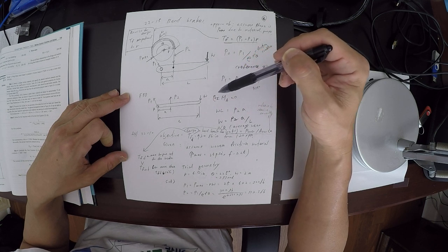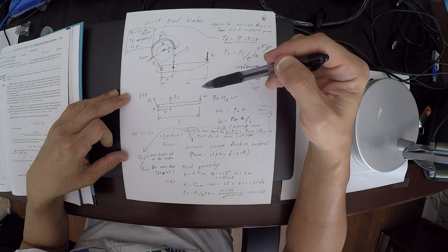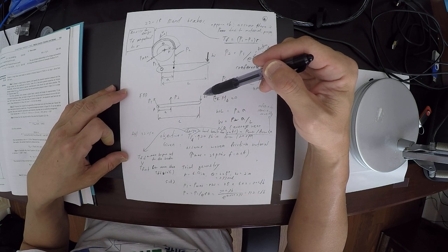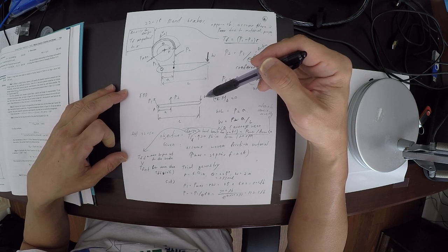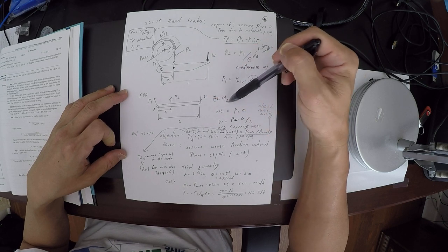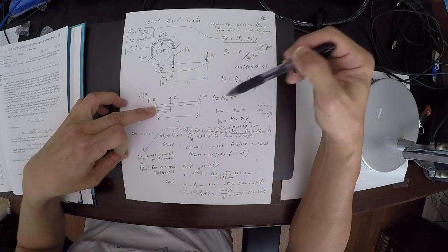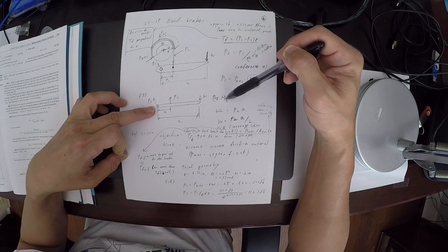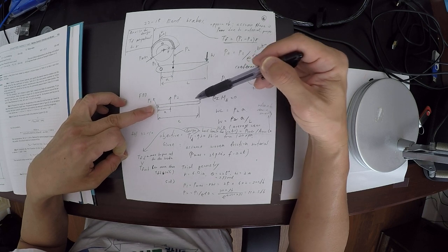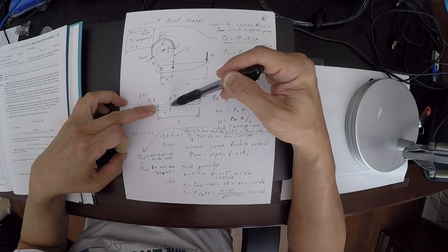So let's see how we could find the W here, by the same procedure that we applied for the drum pad. Here we have the moment equation set for the point A, the rotational center A. So assuming clockwise positive, WL should be positive right here, and then it should be equal to P2 times a.